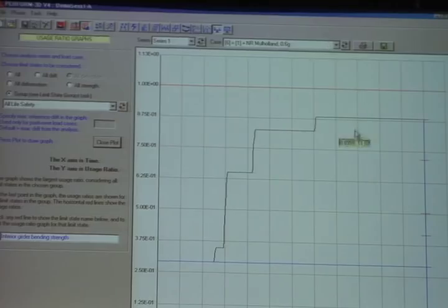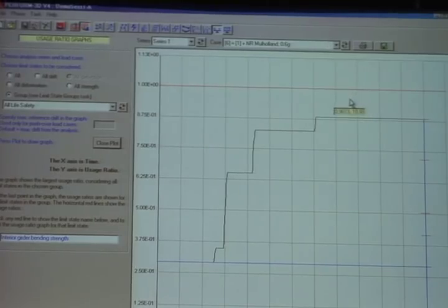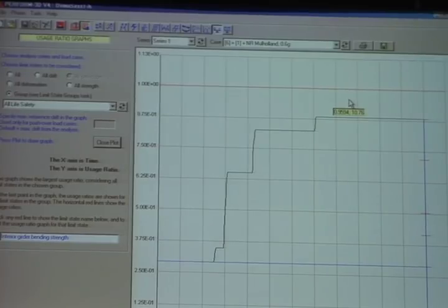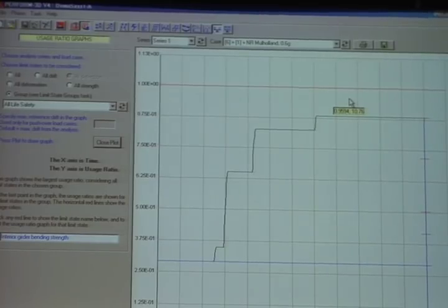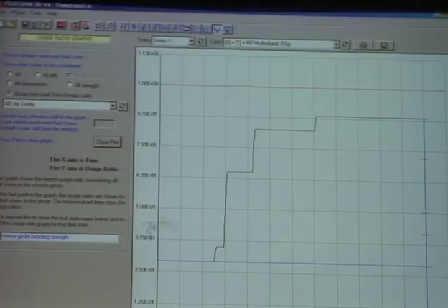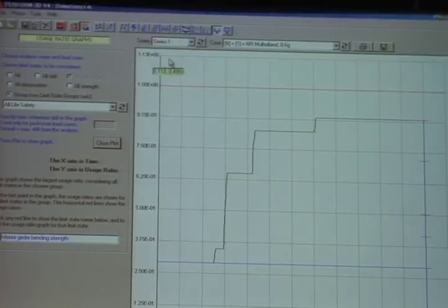Now that shows what happens for a single earthquake. And basically here is the 1.0 level. If everything is below 1.0, you've satisfied all the performance requirements. If any of these limit states is above 1.0, you have to do something, maybe revise the design. Now, that would be what you would do for the case where I said that you use the maximum, the worst hinge.